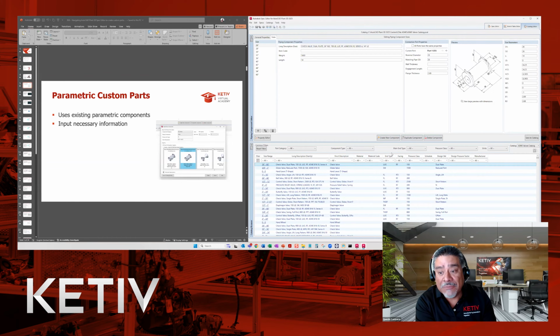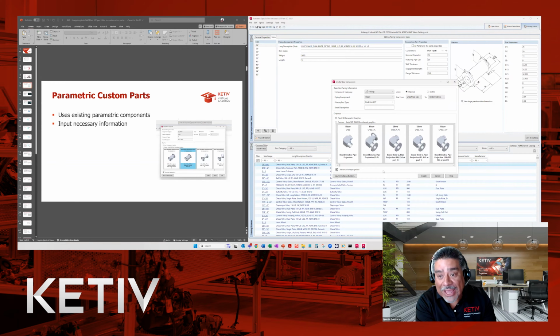So basically, with parametric parts, you're going to create a new component here. So over here on the catalog, I have to have the catalog editor tab active right now, and I can jump over here to my create new component. When I do that, it's going to give me all of these different items that I can choose from. So right now we can look up here at the top. We got components, we got piping components. If I select here on component category, I can see the different types of components that could be used with facilitating the need that I have for a specific part. So I'm going to jump over here to valves because it's kind of common that those are going to be needed.